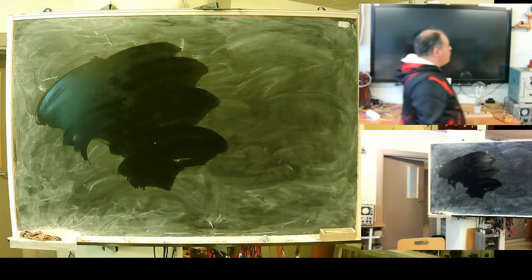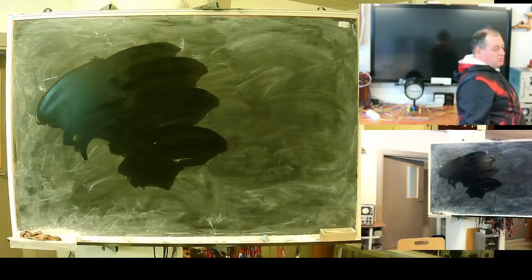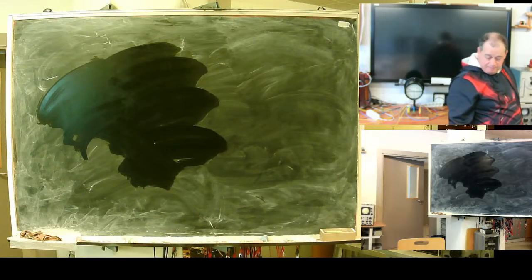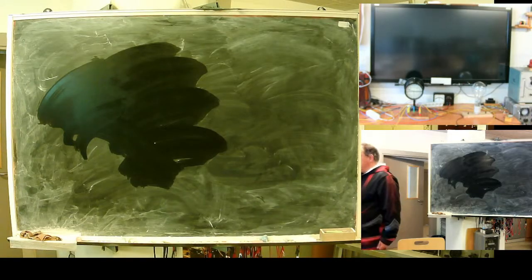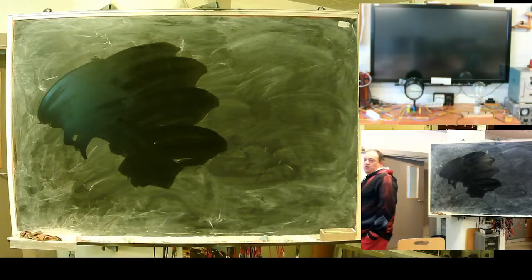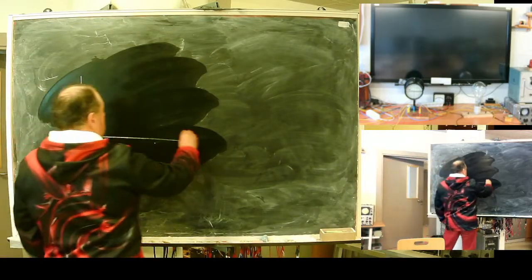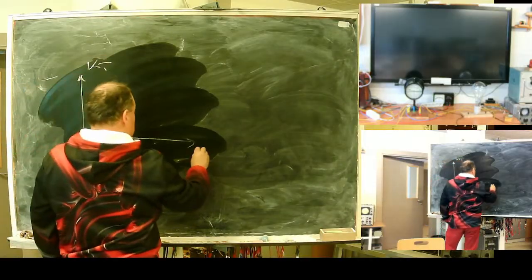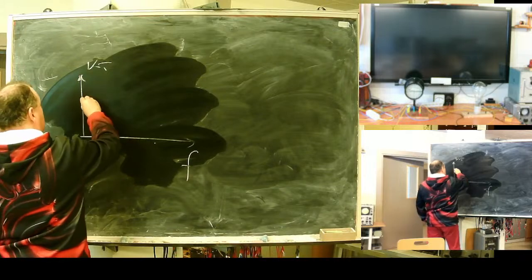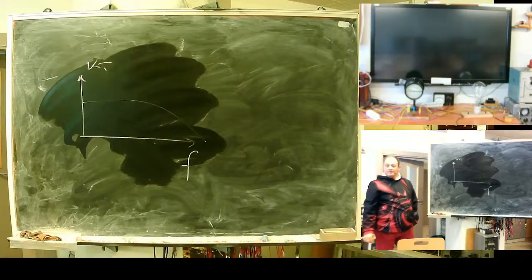Transformer. Actually, for voltage transformer, it's not so large a problem; for currents it is. Next moment: frequency response. If you analyze the range of an ordinary transformer with steel, the transformer ratio as a function of frequency appears to go down.